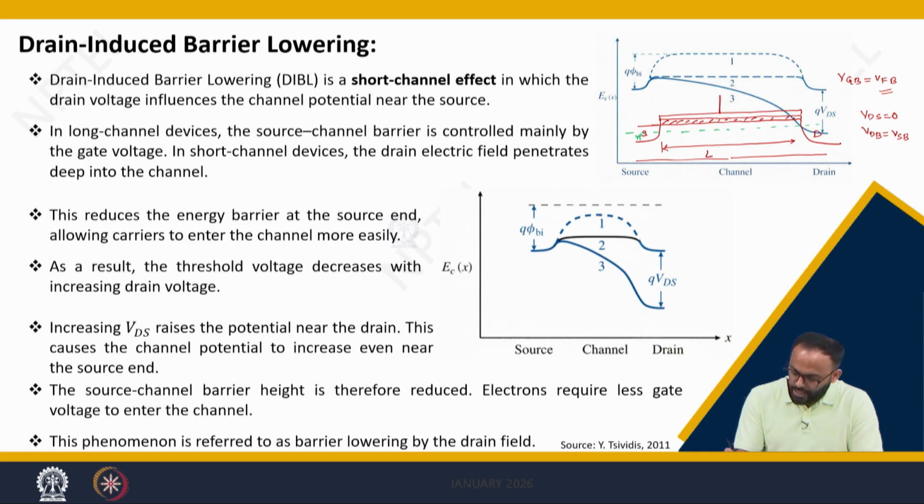One is N plus P here and there is a PN plus junction here. Considering there is no current flow because of these biasing conditions, as the gate voltage is just equal to the flat band voltage and there is no drain field, the Fermi level is aligned. When you make a band diagram at the N plus side you will get this conduction band and this valence band. Similarly, at the drain side you will get the same structure.